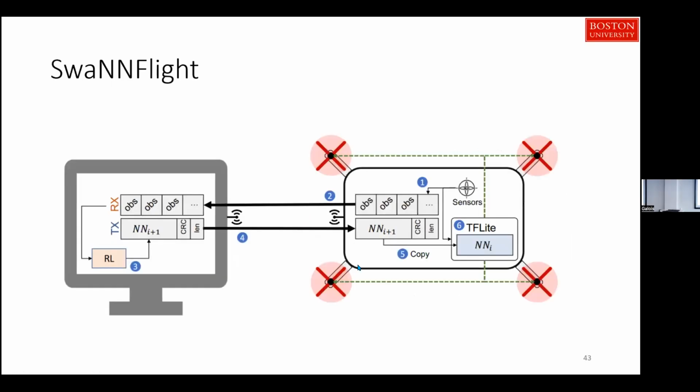So we took the reinforcement learning algorithm that was training these policies in simulation, and instead we allowed communication between the drone and a base station, and we got data from reality, and we got this reinforcement learning algorithm to adapt the policy to what we're seeing in real life. Our hypothesis was that we could achieve higher performance when this gap between simulation and reality is not there.